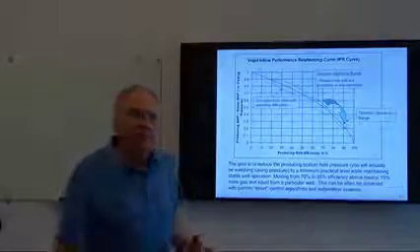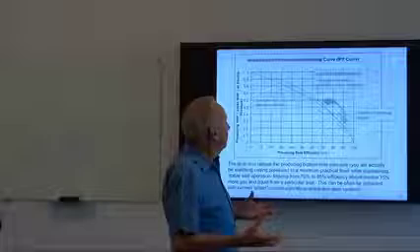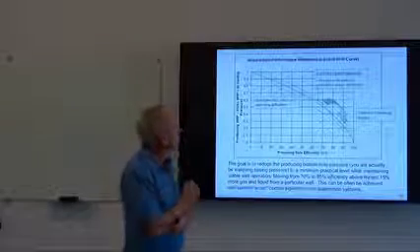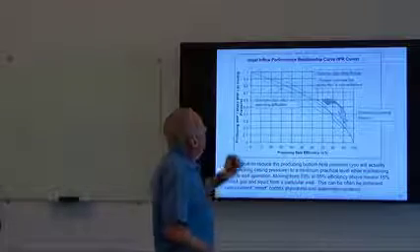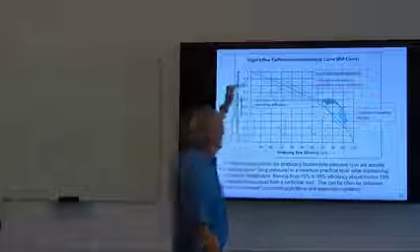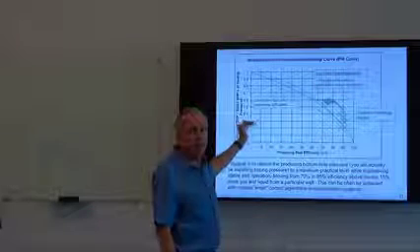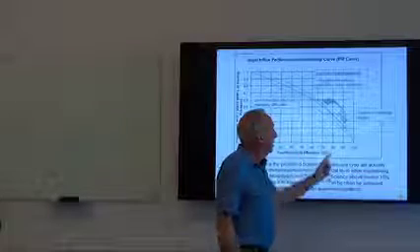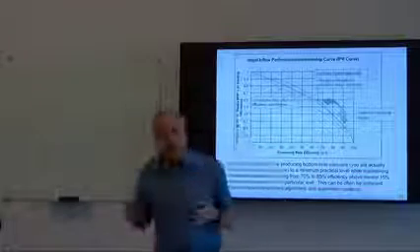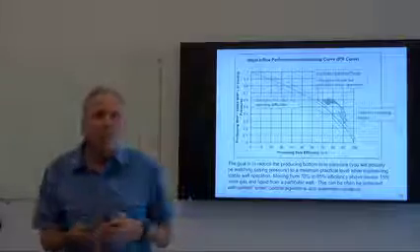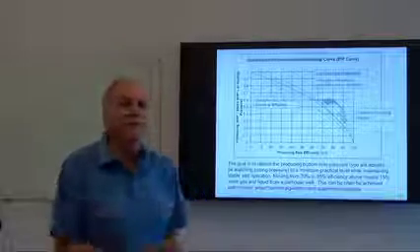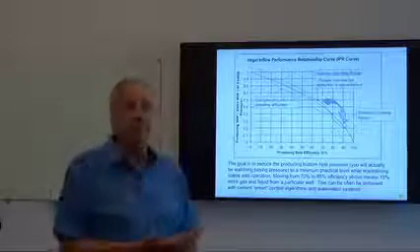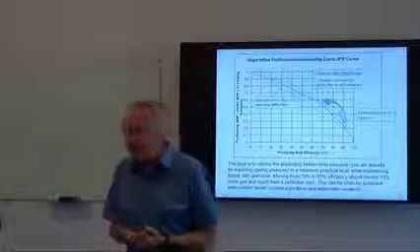So much like we saw in the previous illustration of the inflow performance relationship, or IPR curve, it's still driving us in the same direction. Lower flowing bottom hole pressure will result in improved production efficiency. And this is from the inflow standpoint. So we're only talking about what we're bringing in at the tubing intake. That's what we're really trying to pay attention to.